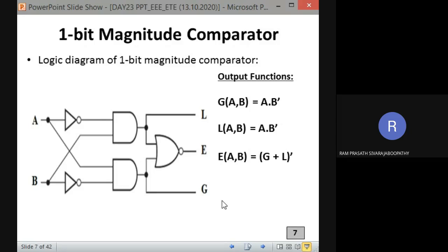I am saying 2-bit magnitude comparator. So here 1 bit means AB simply. If I am saying 2 bit means A1 A0, B1 B0. Yes, very good, Sabri. 4. Okay. Very good, Srihari, Jeevita, Jayavardhani. Okay. So in that case also you can go with K-map table. Correct? So for that you can go ahead with a K-map.